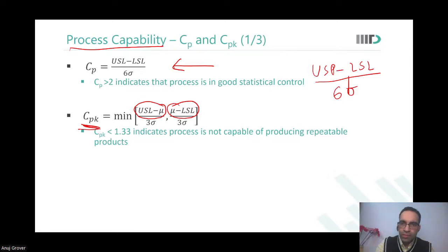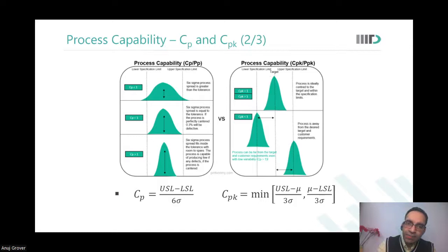Your design is crossing the upper and lower spec limits, therefore it is less than 1. CP exactly equal to 1 means that plus minus 3 sigma of my curve lies within the specification limit, so the failure rate would be 0.3%.